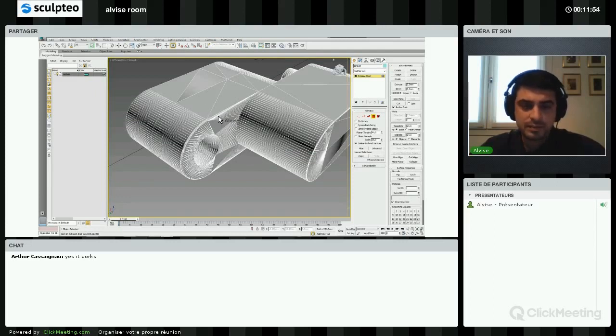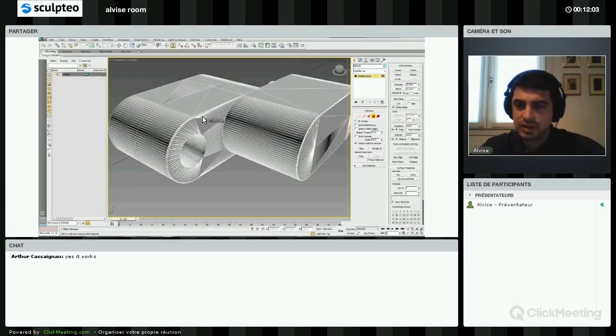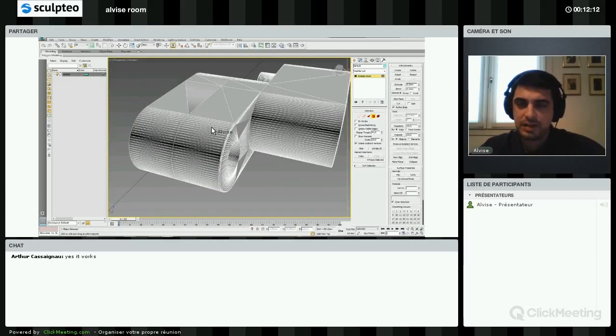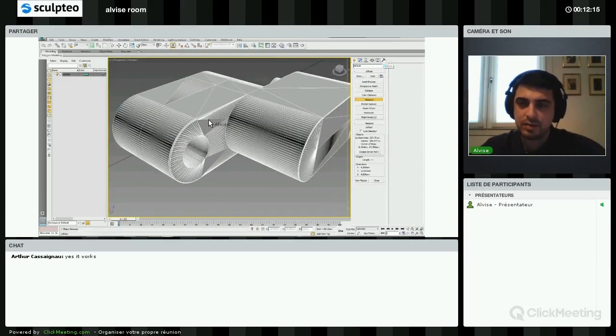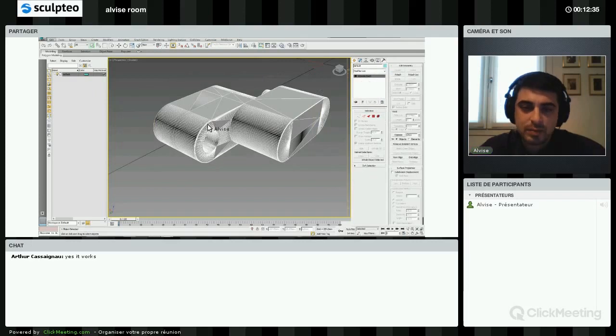So first, as I said, move all this face further, 0.4 millimeters further. Check if the dimension of the parts are correct. Yes, it's 4 millimeters in the Z. You can find all the dimensions about the parts in the utilities tab, this hammer symbol on the right top of the screen. So let's go back to the modify tab and use the polygon selection to select all the parts that I want to move away from the rest of the body.